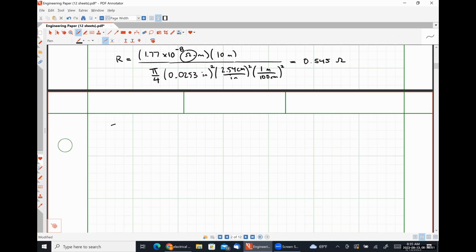So a short circuit is an element where we literally have a wire connecting 2 points. The resistance of this thing, we are going to treat it to be 0 ohms. It's not really 0 ohms, but for the purposes of this class, we're going to call it 0 ohms. And thanks to Ohm's law, if the resistance is 0 ohms, what does the voltage drop have to be across a short circuit? 0 volts.